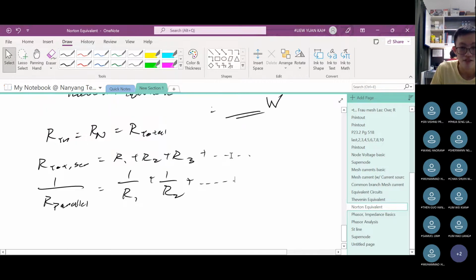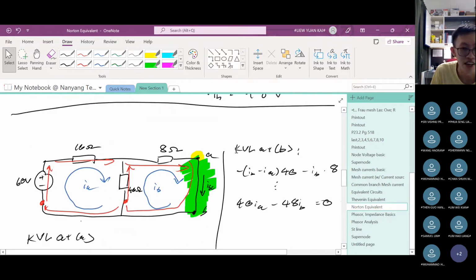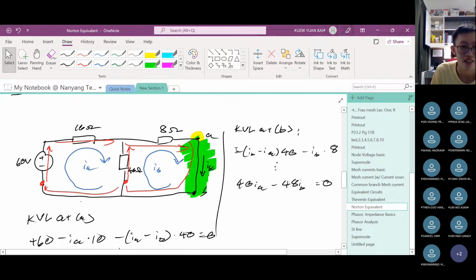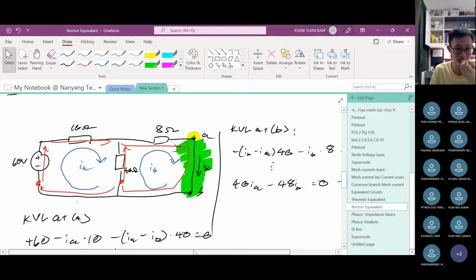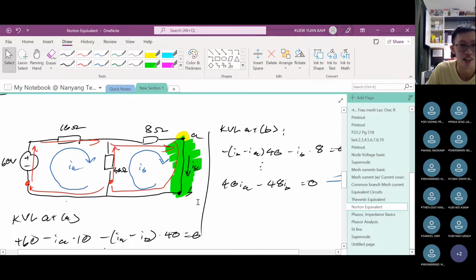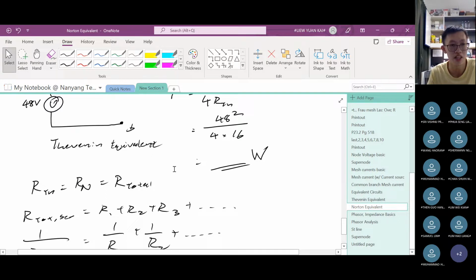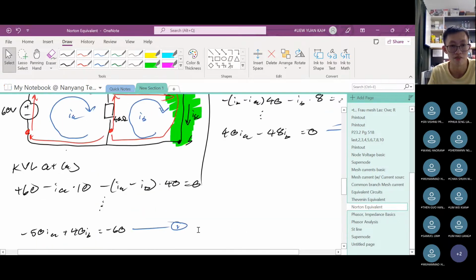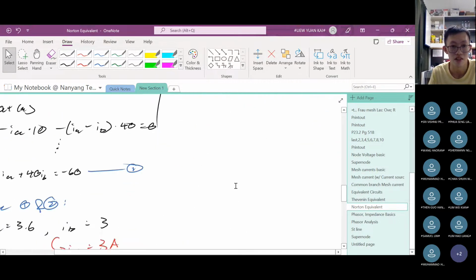But you want me to prove it to you? I'll prove it to you. Let's try this circuit that I drew. How do we find the resistance using the old-fashioned secondary school way? The steps are this: whenever you see a current source, you open circuit it. Whenever you see a voltage source, you short circuit it. In this case, we have a voltage source, so let's short circuit it. I'm going to redraw this diagram.